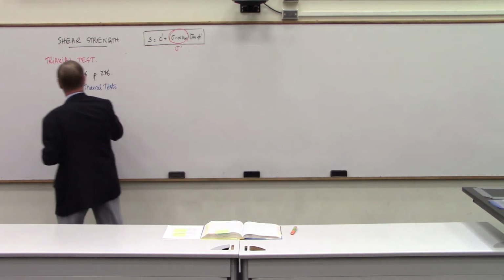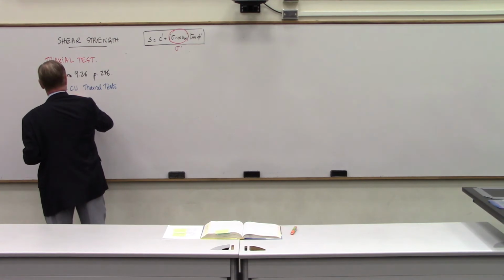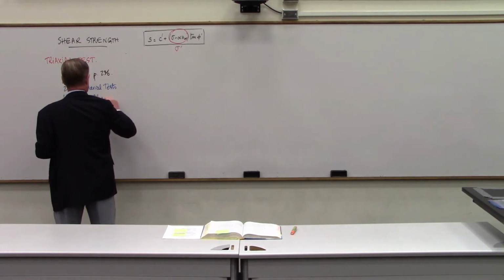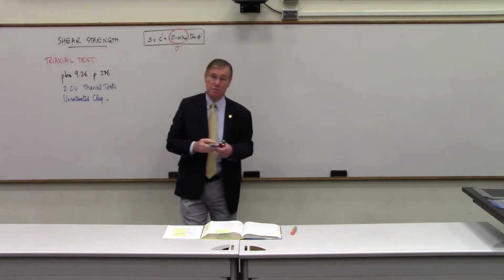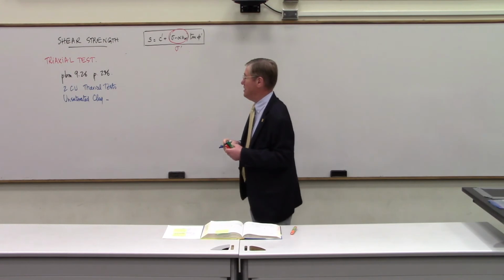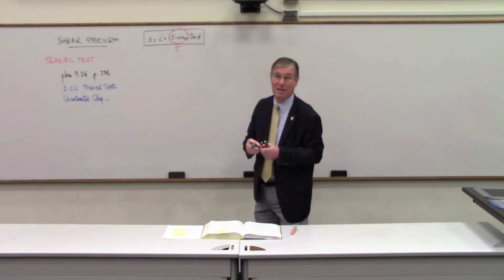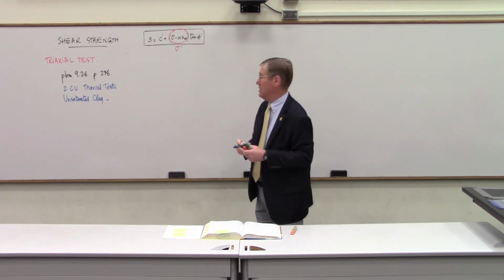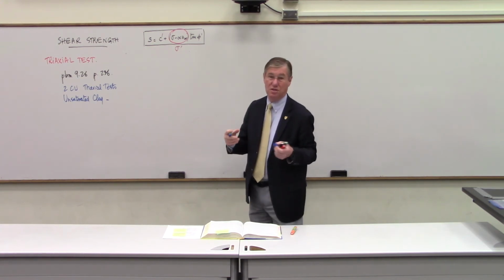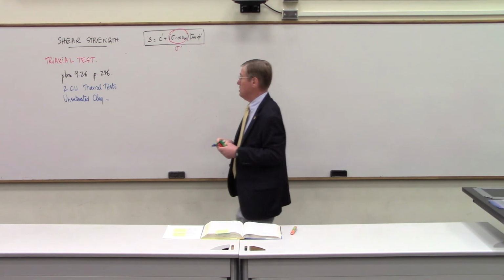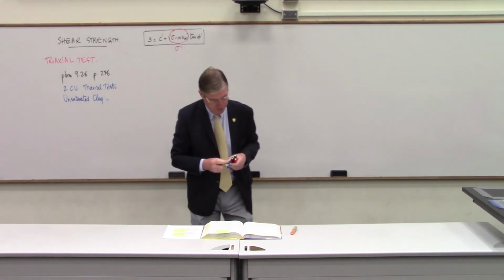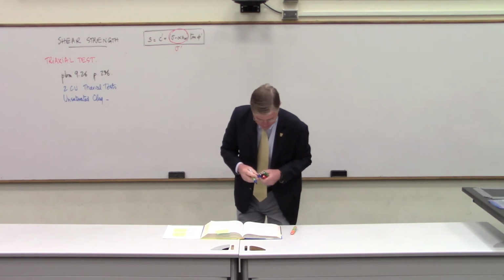All right, so that's the unsaturated clay. So that's the most difficult case, I guess. It's unsaturated, so we're going to have the water area ratio to contend with. And then clay, we cannot assume that C is equal to 0. So that's probably why the problem says 2, because we need 2 to be able to find the envelope.